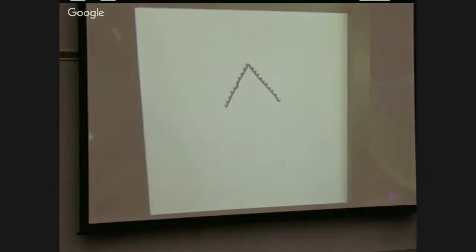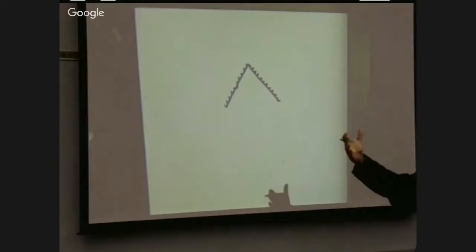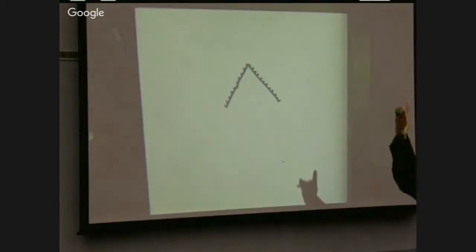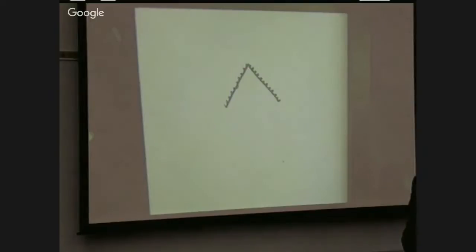And so if you want those little bumps to be smaller, then you change either to a bigger radius, right? Or a smaller step down. And there's a limit to how much a bigger radius is going to help, right? The bumps can just be more spread out. So the thing that really makes a smoother surface there is smaller increments on the step down.